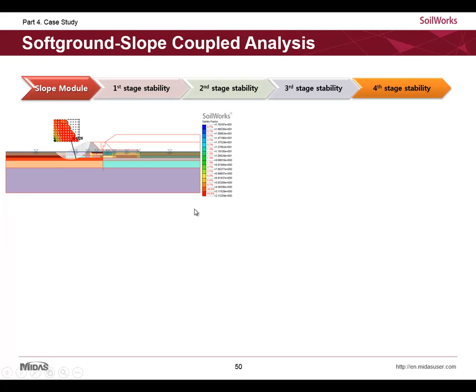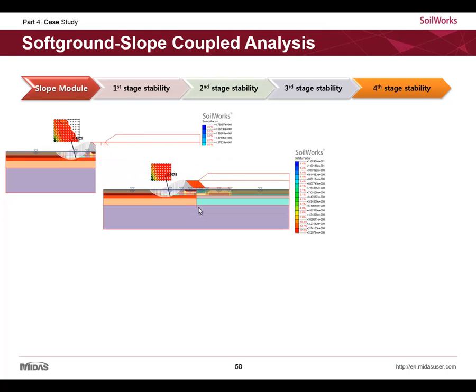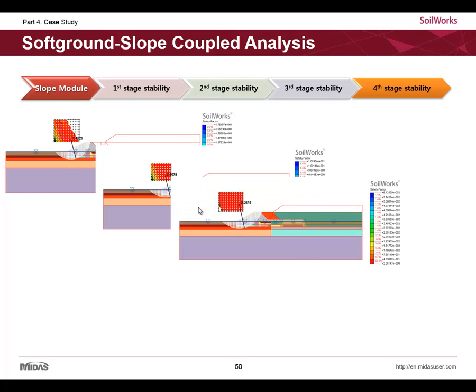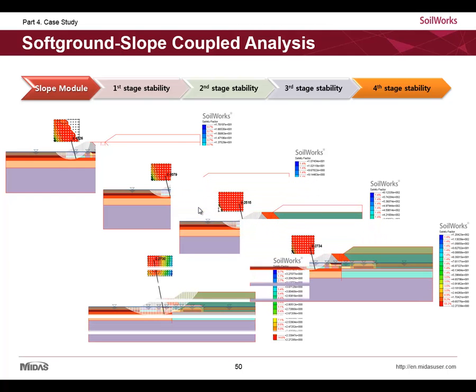After that, you can check the slope stability by limit equilibrium method like this for each stage, before and after accounting for the increase in soil strength. If the factor of safety is less than the design criteria you apply, you can go back to consolidation analysis and change the SCP substitution ratio or spacing to ensure slope stability.